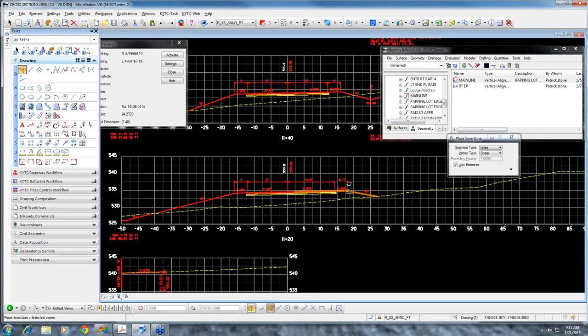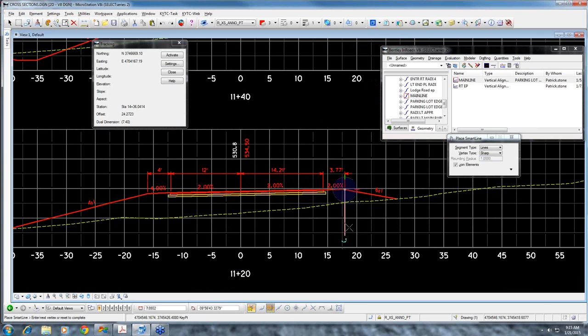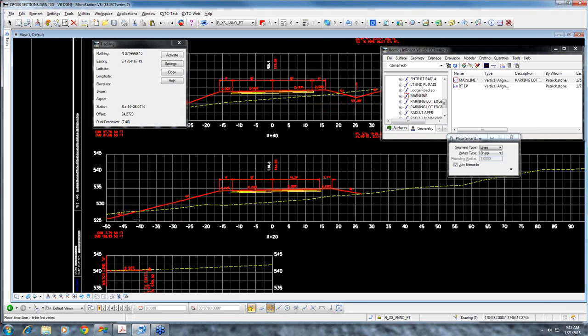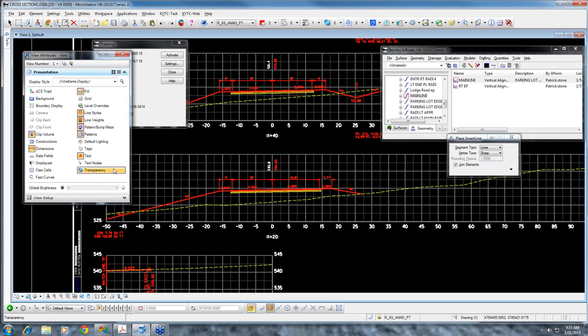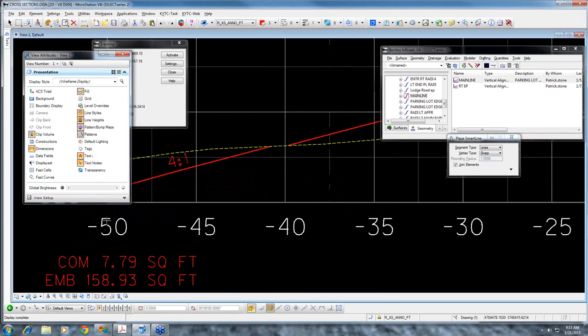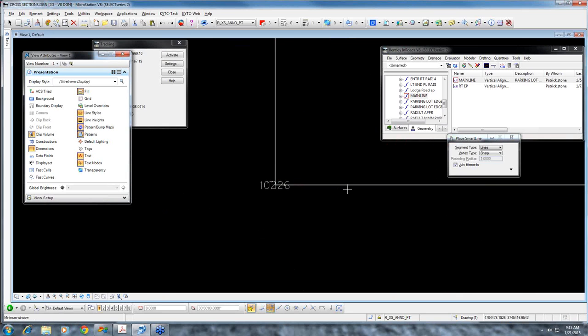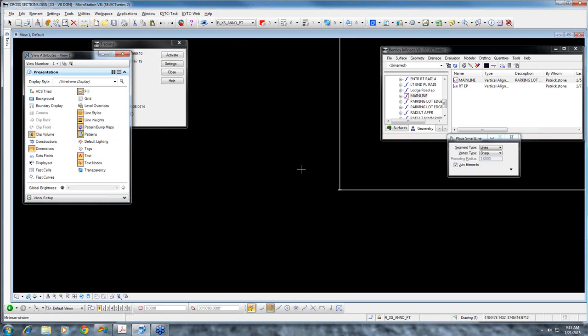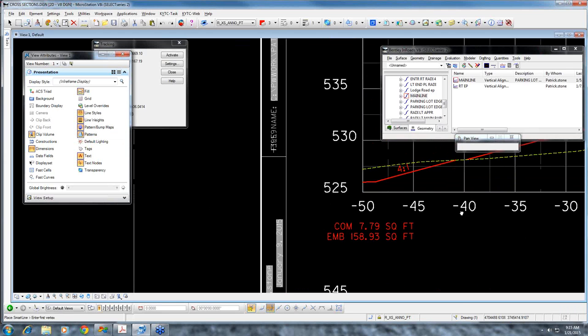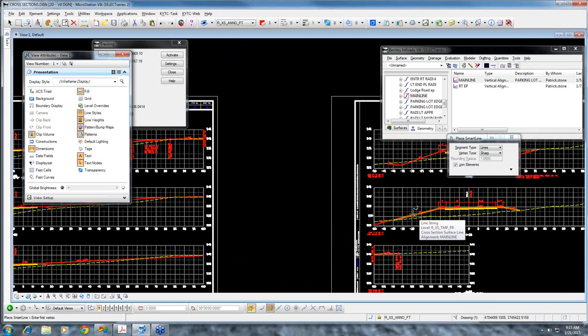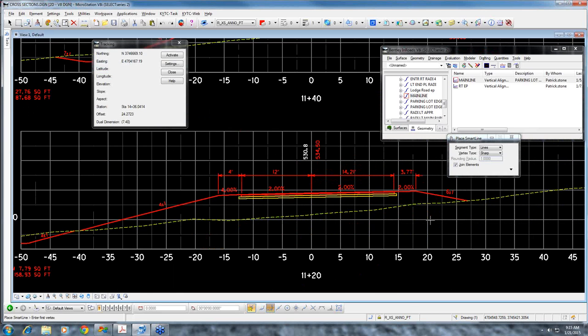It just works from this baseline here for the delta offset. One thing that I did want to point out is when you cut these cross sections, and I'm sure most of you know this, there's a text note in here. If you get somebody in there moving it around and cleaning up your cross sections for you, and this gets deleted, that's when you lose your intelligence in your cross sections. So just make sure if anybody's in there manipulating any of this, they don't delete those text notes, because that's where your information's stored, and it'll mess you up.